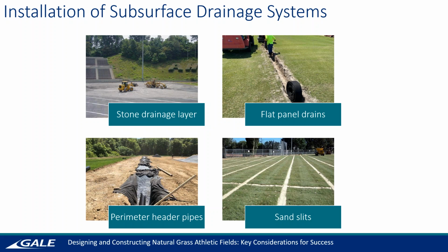That's a stone drainage layer that would go underneath your soil media and your turf grasses. Depending on what we're using it for, whether it's just for stormwater management or just to get drainage going out of there, it's typically between 2 to 4 inch stone drainage media that would get bridged with the soil media on top.